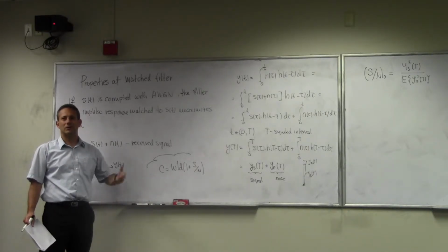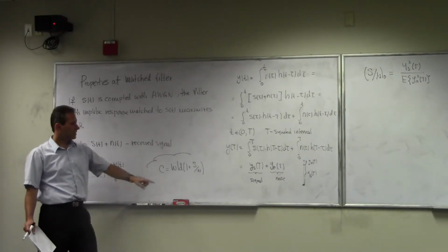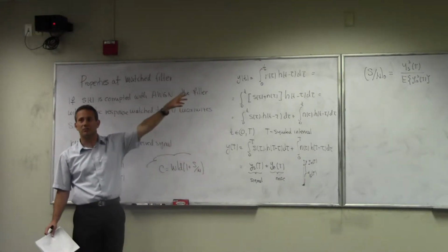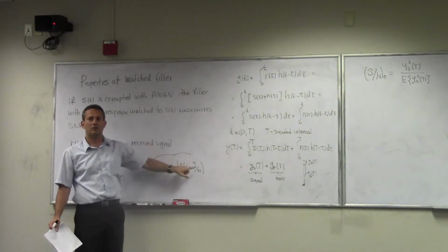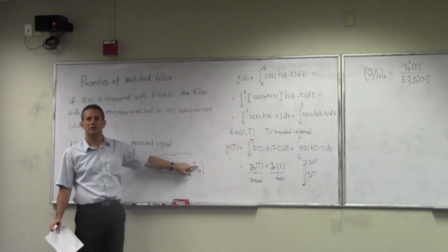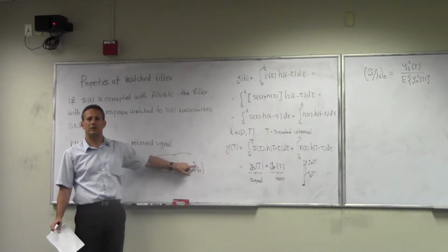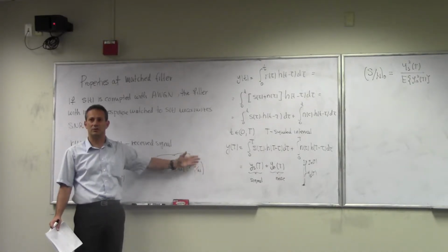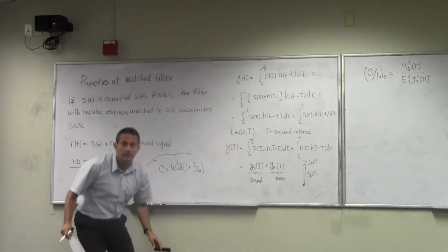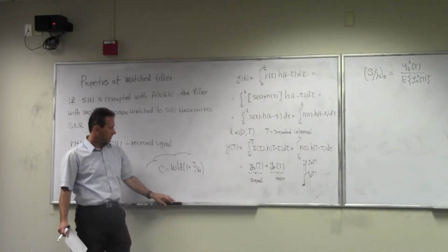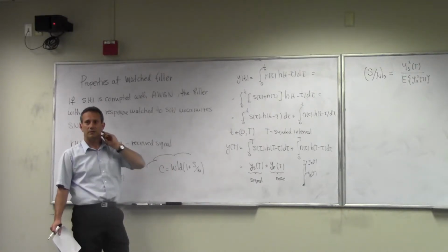Well, you have to give me the context. I don't know why I mentioned that. This is the same signal to noise ratio, the one that we based our decisions on, right? It does change, because even if the noise is constant, depending on the attenuation of your channel, the signal will change. The signal to noise will change. But that's the Shannon capacity formula, which is a little bit different than this.